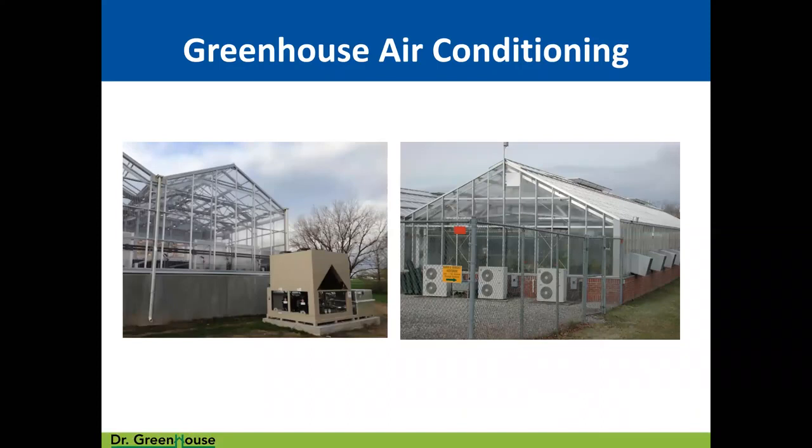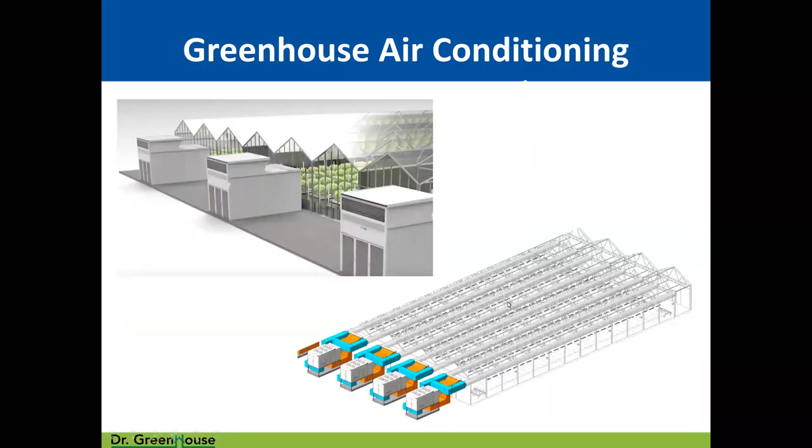Okay, we can air condition a greenhouse. I don't usually recommend it. It's insanely energy intensive, and we want a very well sealed greenhouse if we can, not this, with this vent up here, if we can help it. Maybe this is a day that they don't need air conditioning, so it's a hybrid greenhouse, so I approve that strategy. But we can air condition a greenhouse, and there are a lot of different ways, right?